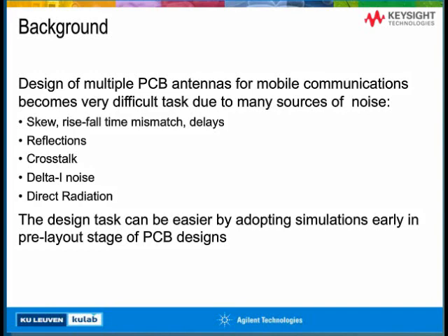With power integrity, you have simultaneous switching noise. You can have direct radiation from components and from interconnects. So it is quite a difficult task, but luckily you can make it easier by using simulations early in the pre-layout stage of PCB design.